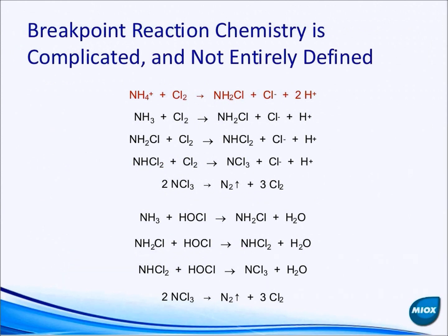I won't go into excruciating detail, and I will not go through every single one of these for you, but to put it mildly, breakpoint reaction chemistry is complicated and is not entirely defined. This is just some of the many reactions that can be taking place, and some of the side reactions and intermediate reactions in the process of actually oxidizing the ammonia.